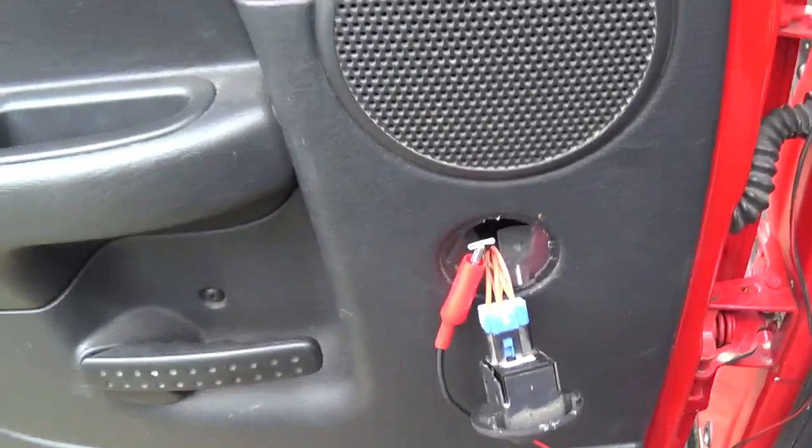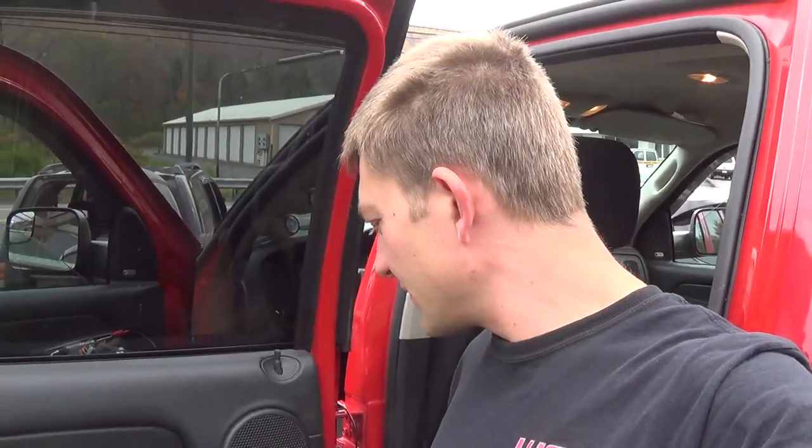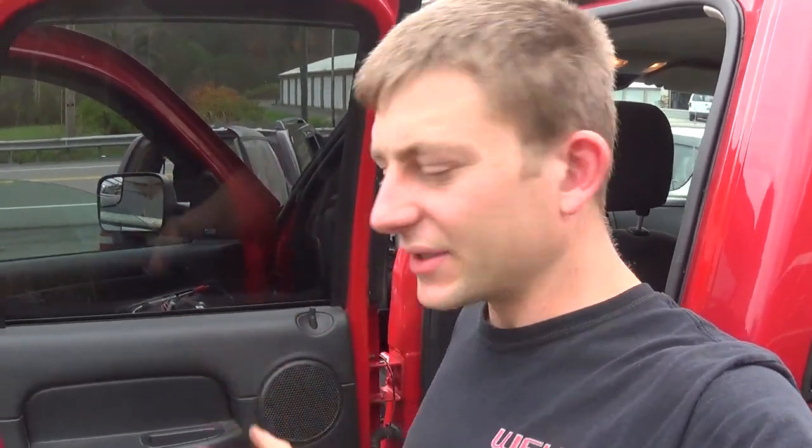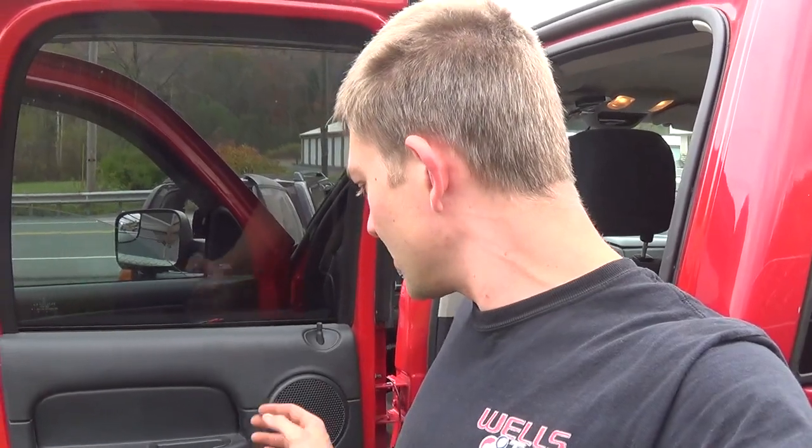So I think there's more than one issue here. Okay? So let's see if we can follow along. On the tan wires here, we are getting a voltage. Test light's bright, but only from the master switch. This switch here is acting the same as the other two passenger side doors, meaning it's not doing anything. But this motor here, it's also not doing anything, even with voltage on those control wires. So one issue I suspect here is something to do with the motor in here.